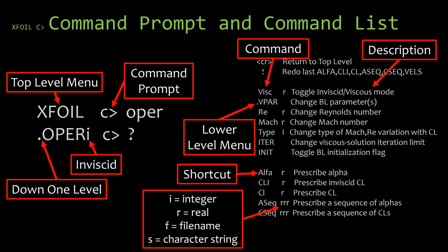Now let's say I was at the OPER menu right there and I typed in the question mark and hit enter. Then I would see Xfoil spit out above the new command prompt that follows this list of commands and sub menus that you see here on the right. So let's look and see what we have there.